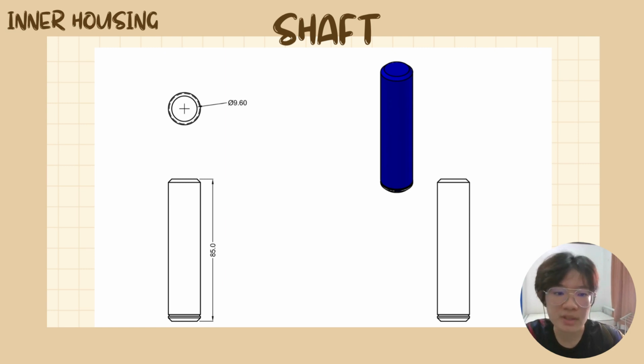shown in the diagram. So on the top and the bottom of the shaft, we added a 1 millimeter chamfer to improve the design. And the shape was rotated 360 degrees at the tip of the shaft area. And finally, we kept the remaining cylinder while subtracting the revolving form.